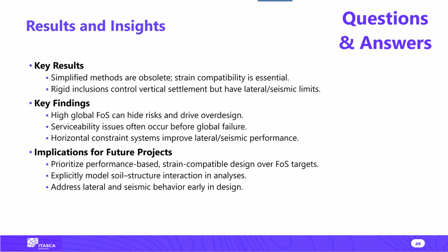From the shear wave velocity profile, knowing the density, you can estimate the Gmax, G0, for the soil, and therefore the Emax. Once we know the Emax, I tend to divide by 3 to get the E unloading-reloading, not the reference. For a sand, 2.5, let's call it 3. If I'm in a clay, I tend to use 5. If I'm in an organic material, I tend to use even 8 or 9 to get the unloading-reloading.